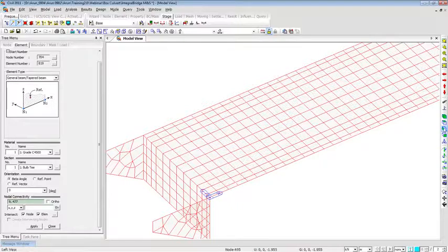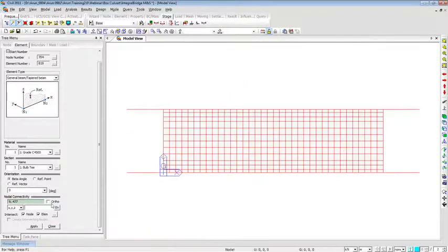Now I'll go to the top view and create the diaphragm. So I'll switch the element from bulb T to diaphragm, and diaphragm divides this 36-meter bridge into 3 parts, 12, 12 and 12. So I'll just move across the bridge and see the location where I'll get 12. So you see here at the status bar at the bottom of the screen you can see X is 12.